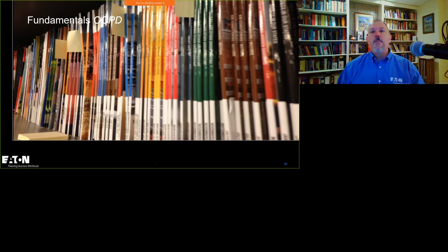If you haven't set these breakers, you'll probably want to take that down, do your maintenance things anyway, program those set points and get that back up and running, because you never know what the loads are downstream and all the different things. You don't know what the maintenance history of that circuit breaker is. All right, so that's all on that one.